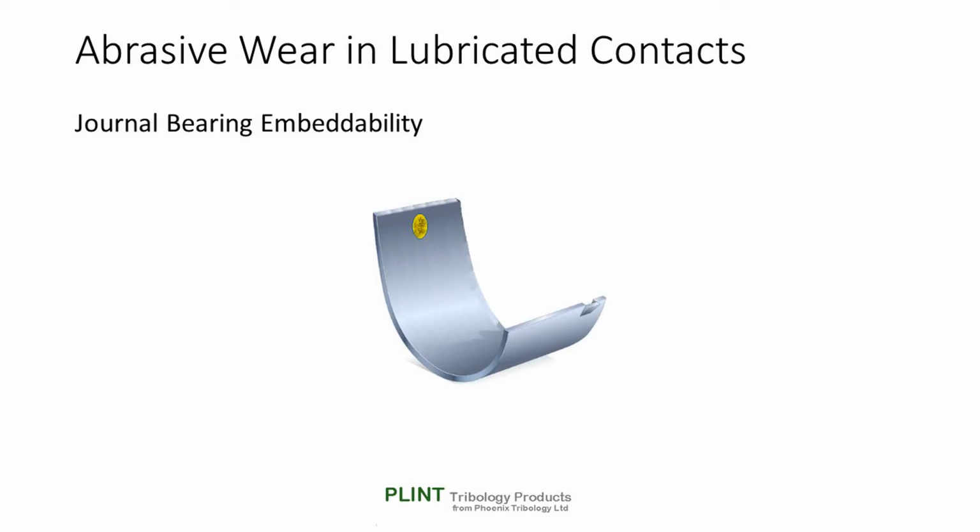Ideally, one would like to control the total mass, size and angularity of the particles passing through the contact. One way of achieving this is to machine a small pocket in the in-running side of the loaded bearing shell and insert a known quantity of well-calibrated abrasive particles held in place with a suitable wax. As the bearing runs and heats up, the wax melts, releasing the particles into the contact.